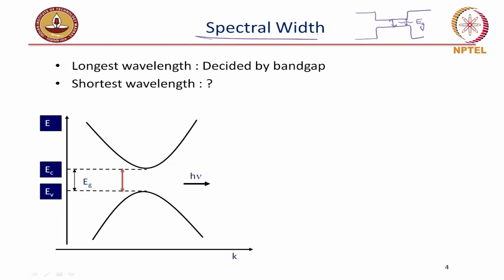So it is very easy to understand that, okay, so this is the energy level diagram or the EK diagram of the semiconductor structure. So here we are talking about the Eg of the active region now. So this outside P and N doesn't play any role now. The band gap of those regions do not play any role. It is just the band gap of the active region which will now decide all the properties that we are going to do next. So as I said, this is the EK diagram, the energy versus momentum diagram.